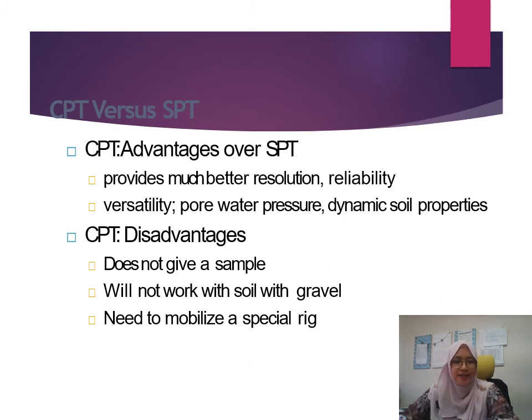So this is the advantage of CPT versus SPT. CPT provides a much better resolution. It is more reliable, more versatile, and we can also determine the pore water pressure and dynamic soil properties from the data.